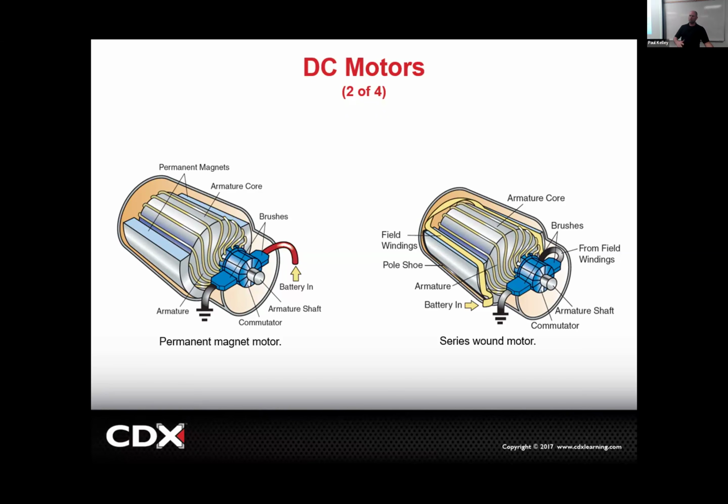So I don't understand. It works or it doesn't work. Like, no, listen. Couple things could happen. If the brushes are stuck and you free them up, it'll work until the next time the brushes stick. But the other thing I've seen is if you look at each one of these segments in the motor, you got a positive and a negative, and this winding right here is what's going to get it moving when it's down here interacting with this permanent magnet.